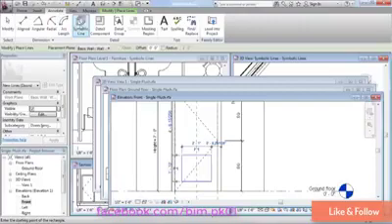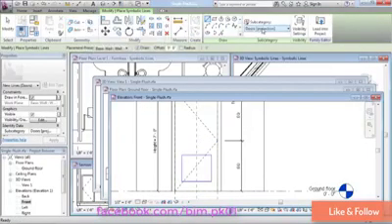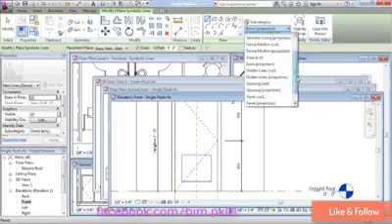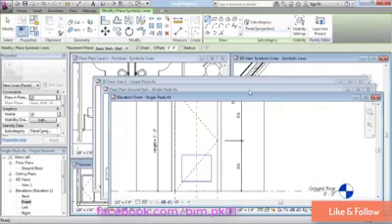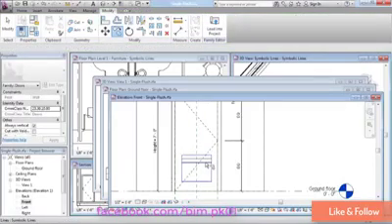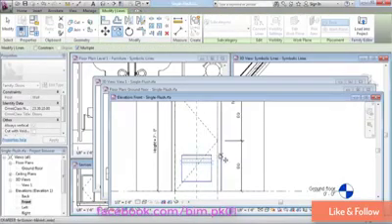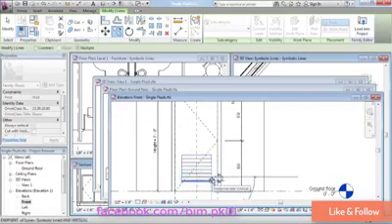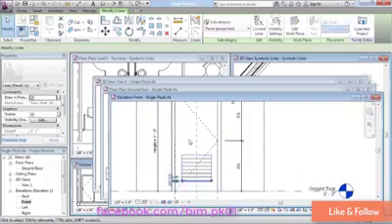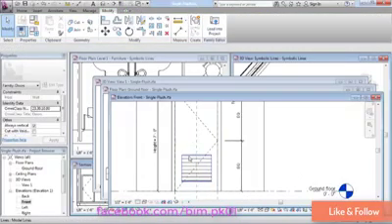I'm going to switch to the Annotate tab, choose Symbolic Lines next, and change the line style that I'm using for these symbolic lines to panel in projection. I'm going to treat them as part of the door panel, and projection because I want them to be the lighter line weight that I'm looking at. And I'll just start drawing some lines here. Now to speed this up, I could switch over to copy, select this and do a multiple copy. Stop right about there. And that gives me the overall representation.